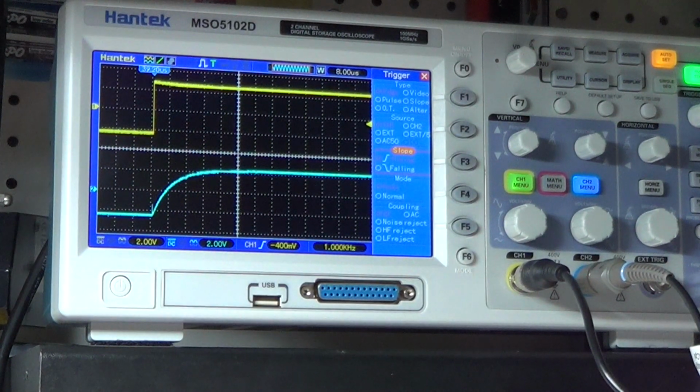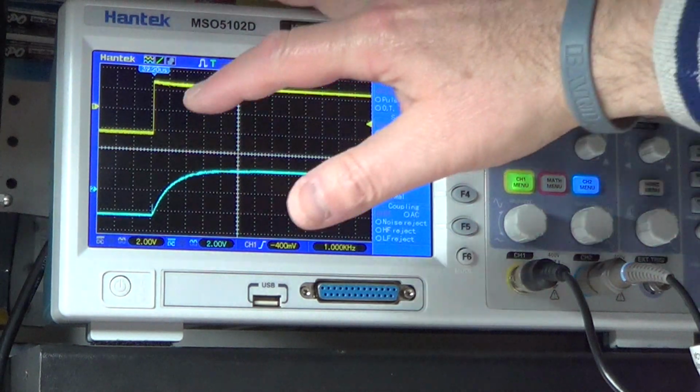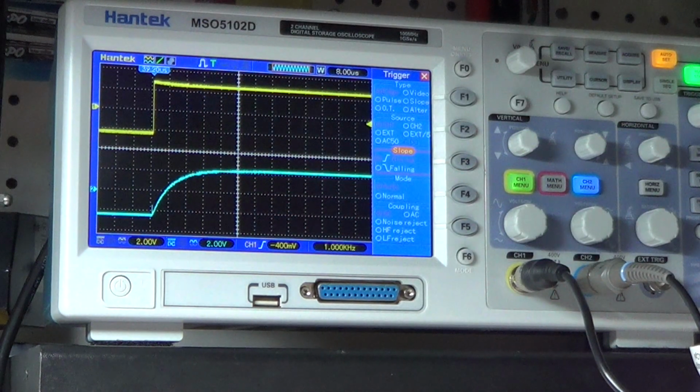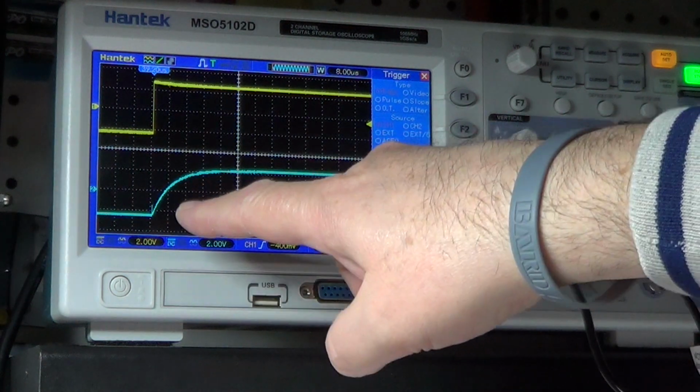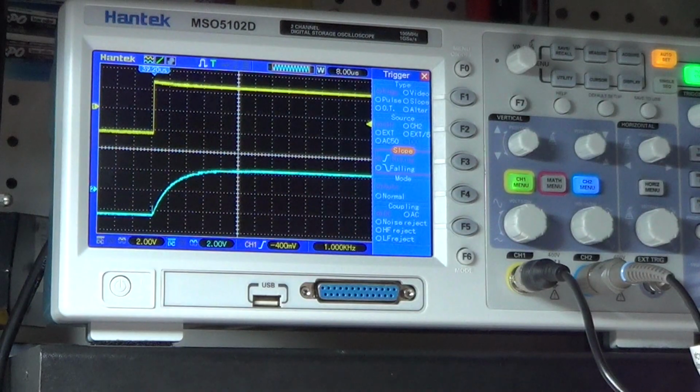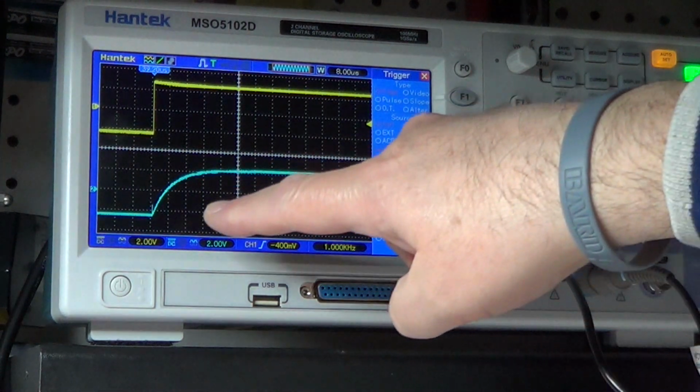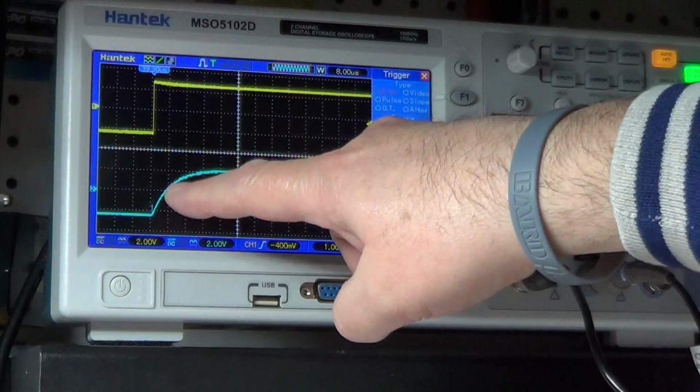So this is the case where the voltage is suddenly increased, like here. Because of the back EMF that we saw in the previous case, the current initially does not flow, but then a little bit at a time, while the magnetic field reaches its maximum, the EMF decreases and the current can increase, finally following the shape of this curve.